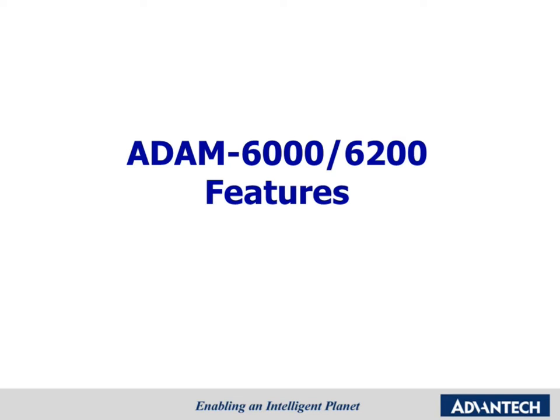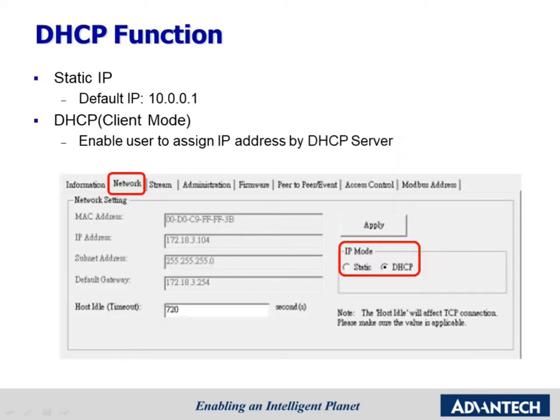Now, we are going to talk about the common features of the ADAM-6000 CE and ADAM-6200 one by one in the following slides. First is the DHCP function. As you can see in the picture, you can enter the IP by clicking the Static IP checkbox. When you need a DHCP server to assign the IP address to the ADAM, you can click the DHCP checkbox. Remember to press the Apply button to apply the setting.